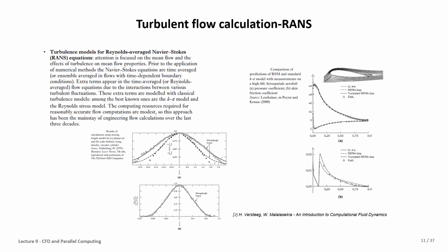Then this is the presentation of RANS, and we can say it's the cheaper approach in CFD for turbulent flow. In most studies, it's shown to be 10 times cheaper than LES, and 10 times is not something that we can ignore, especially for a large problem. So it's one of the appropriate models we can use to deal with turbulent flow.